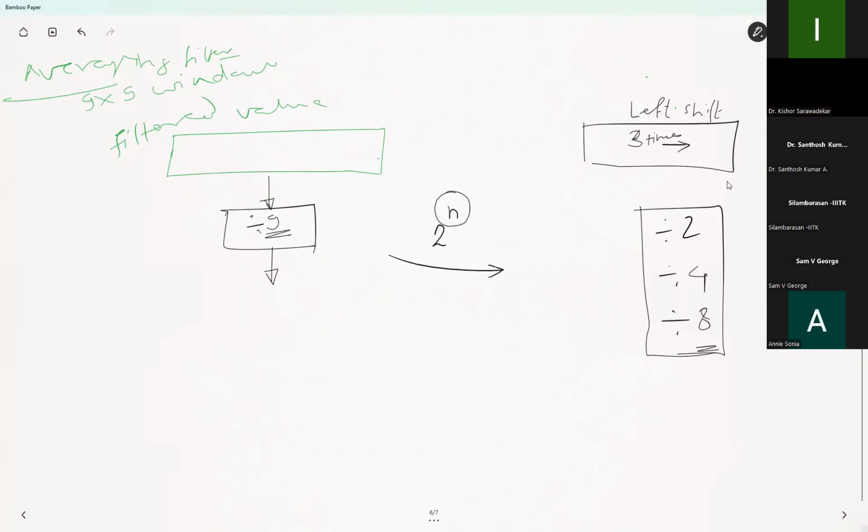It will be a synchronous operation and hence your power consumption, area and speed will be very good. If it is not satisfying your requirement, if you want it to be divided by 9 only, then we need to look at another algorithm. Sometimes ready-made resources are available for a division block on some chips. If it is available, you use it and get the job done. Otherwise, we have to look for division algorithms to implement and get the job done.